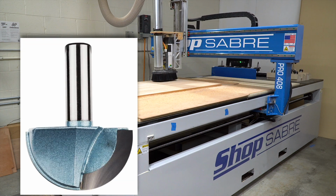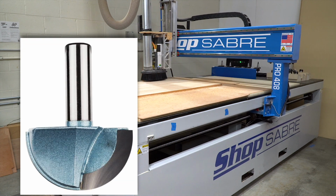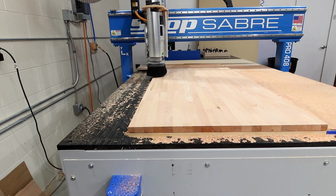Next up is the cove cutter. It's a 2-inch cove, which is essentially a ball mill, but you've got to run that pretty slow, about 100 inches a minute.